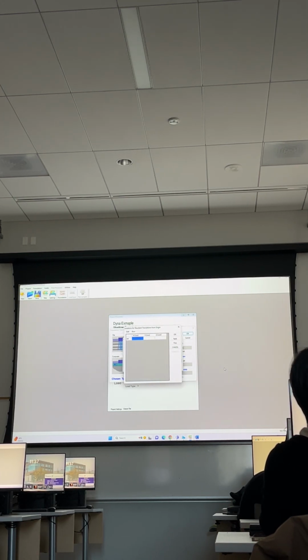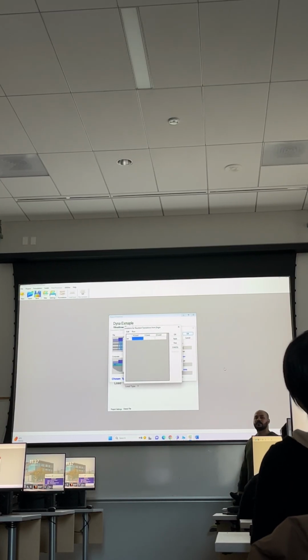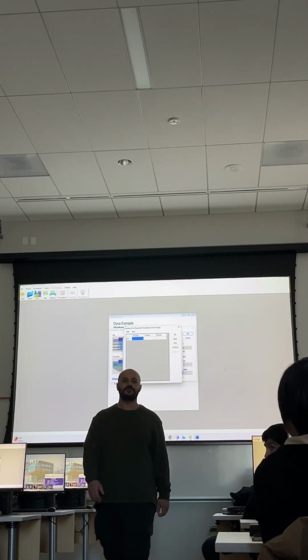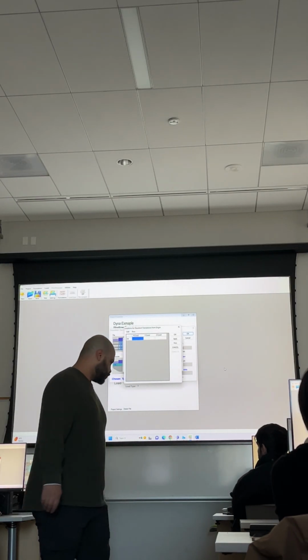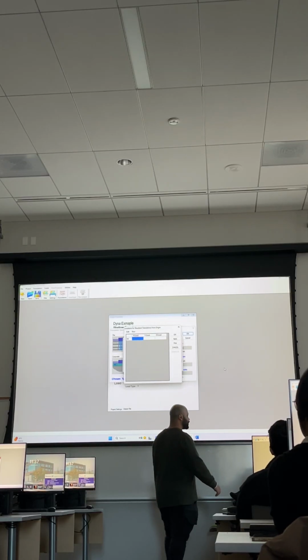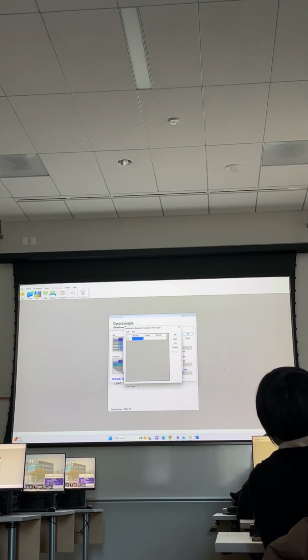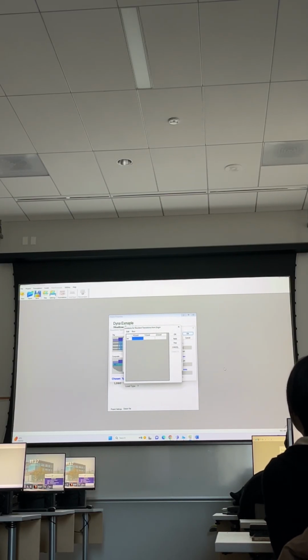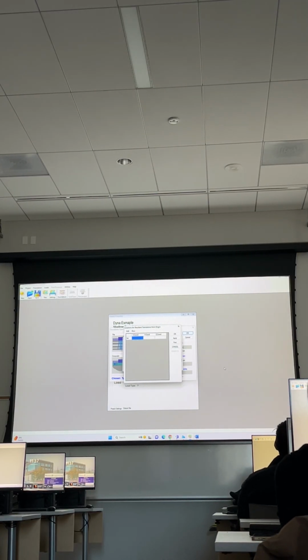I'm sorry, what was the damping? What was the damping number? The damping? Yeah, 0.03, 3%. Usually for soil it's between 2% and up to 4%. You can assume between them. And in your project, Professor Sham will provide you this number exactly, so you don't worry about it.